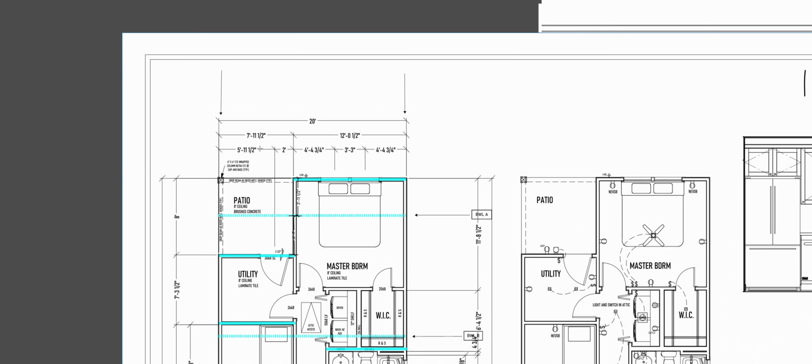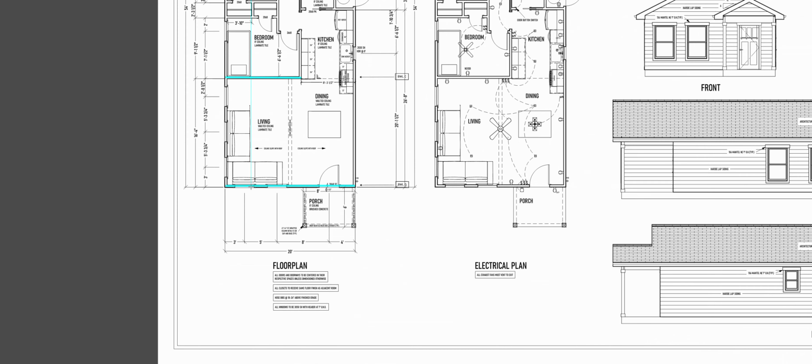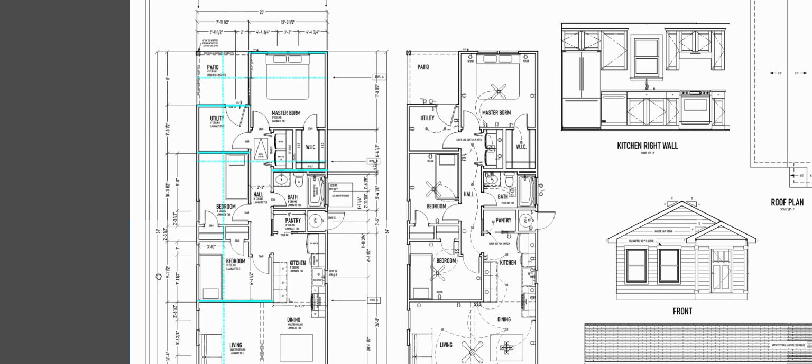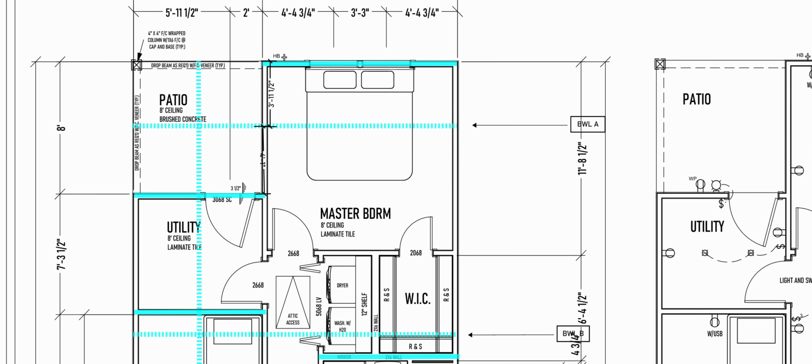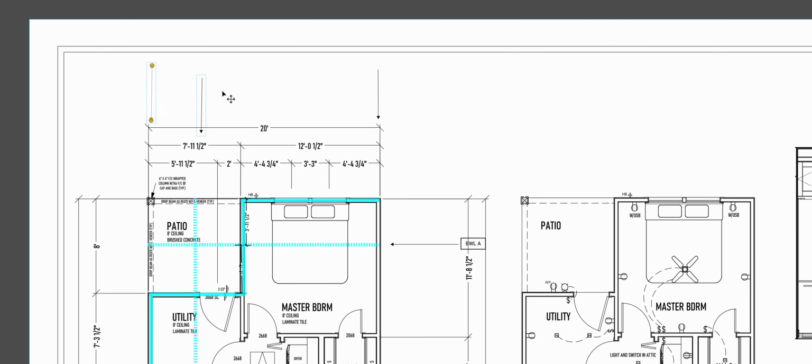But what I can also do, because this is less than 8 feet, is I can just put them in one and go right in the middle. Bring that brace wall line down to here. Hopefully that's somewhat perpendicular. All right, so that's the brace wall line. And the path of the braced wall line is actually from there. It crosses over and it goes down through this wall. So my braced wall line is actually right here.